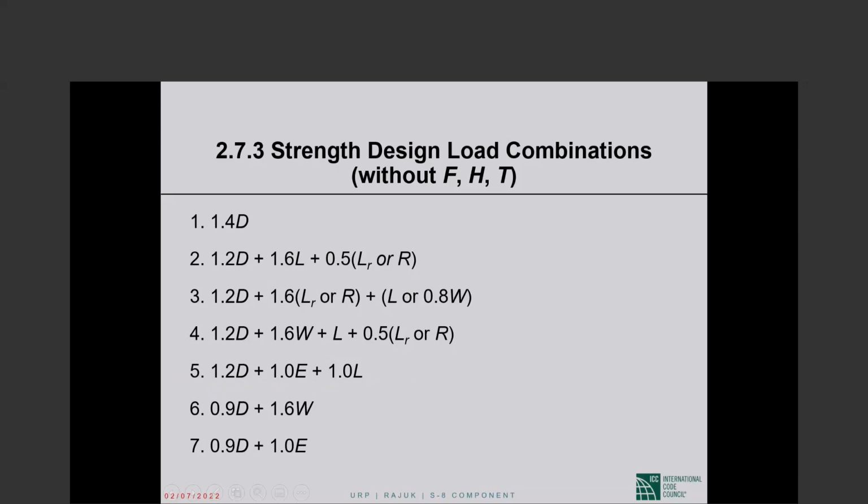Gravity adds to the effects of earthquakes. This is the counteractive load combination. Gravity still causes negative bending moment at our support section, but earthquake causes positive bending moment because earthquake has changed direction. If we want to calculate the smallest negative or the largest positive bending moment at the section, we will use this load combination, 0.9 dead plus 1.0 E.